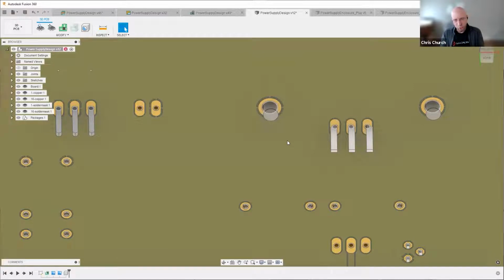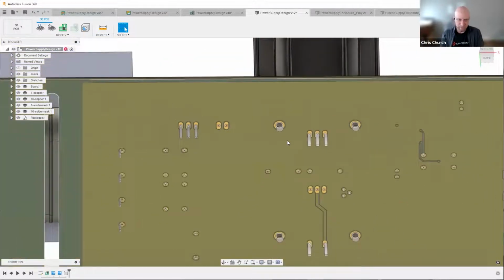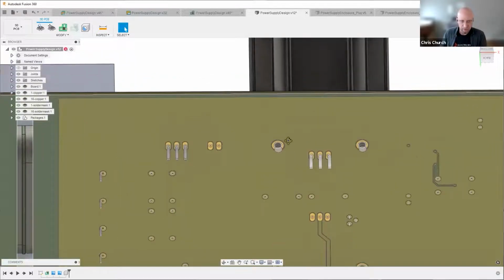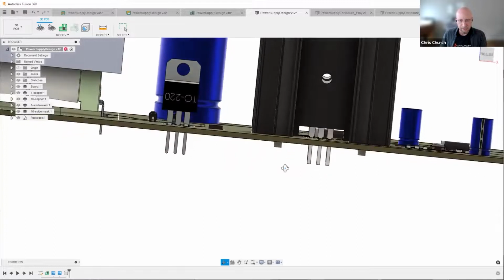What we see as a more successful strategy is we can apply solder there for additional support. But typically, these heat sinks are going to have a hole in them, and those holes are going to be threaded. We'll see that right here, for example, there's that threaded hole. They line up with the hole in that TO220, and that enables us to put a screw in there.